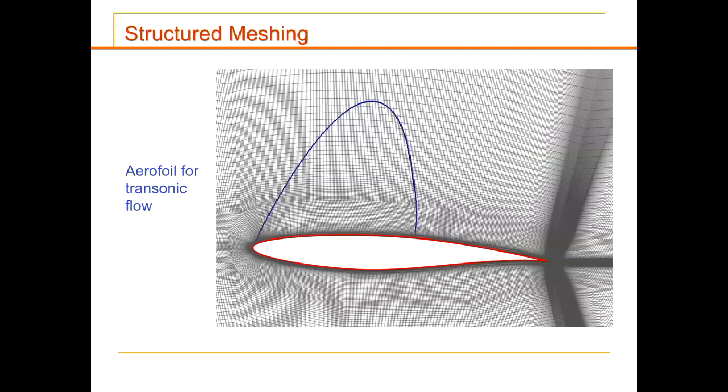Some more. For those who are aerodynamics people, why is it so important to have mesh around the aerofoil? Velocity difference. So what is the term? There's two words there. I want you to get to. It starts with BL. Boundary layer. Exactly. It's to resolve the boundary layer. Why do you need to resolve the boundary layer? Because the velocity changes dramatically from the wall of the aerofoil. True? So that's why you have a lot of mesh around the aerofoil.